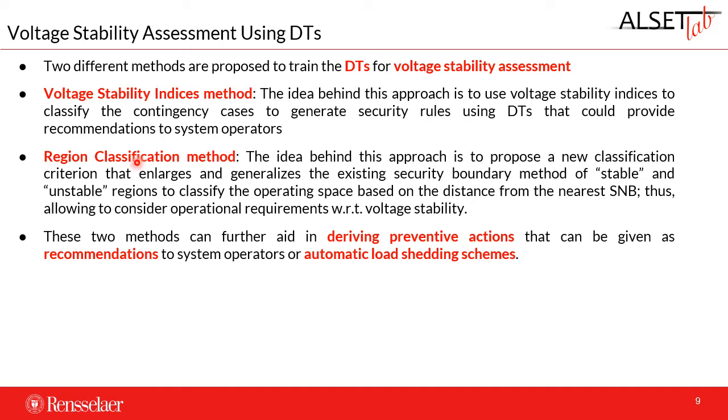The other approach is a region classification method. And here what we do is that we propose a new classification criterion that enlarges and generalizes the existing security boundary that is used, where we simply separate the conditions between stable and unstable. So we want to expand that to have more granularity and to be able, therefore, to provide a better basis for taking corrective actions. So this is going to be based on the distance to the nearest Saddle-Node Bifurcation.